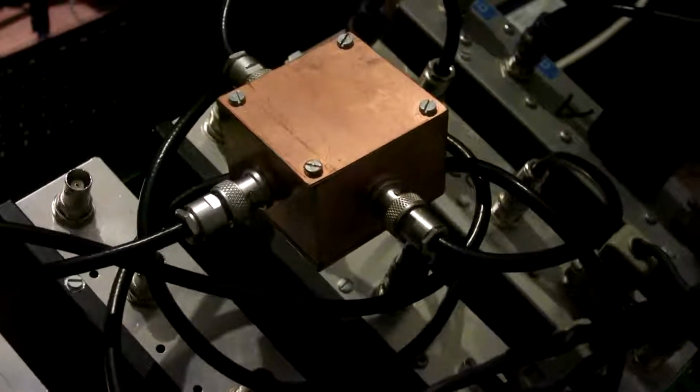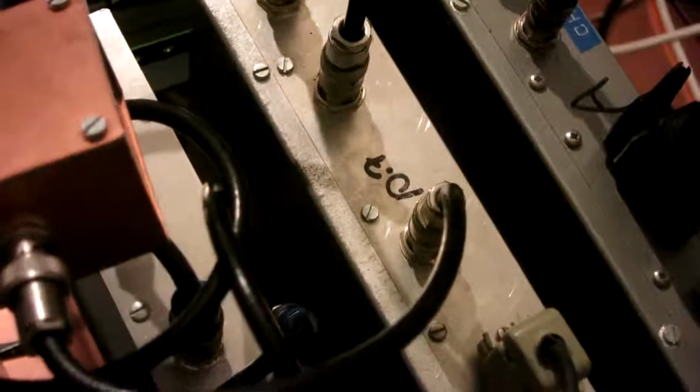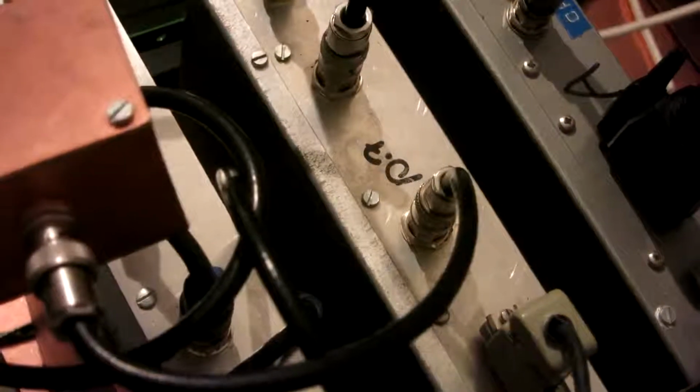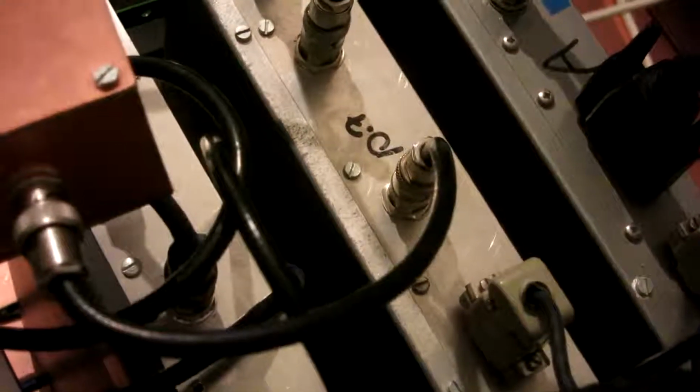Like before, the signal enters the WSE units through a 3 dB hybrid into the 10.7 MHz input. It is not suitable to calibrate on the 2.5 MHz input, because at that point the frequency response is sensitive to the input impedance. But it's okay to calibrate on 10.7 or on the HF inputs, or also on the 2 meter input. It doesn't matter. All the selectivity comes from the 2.5 MHz to audio converter.